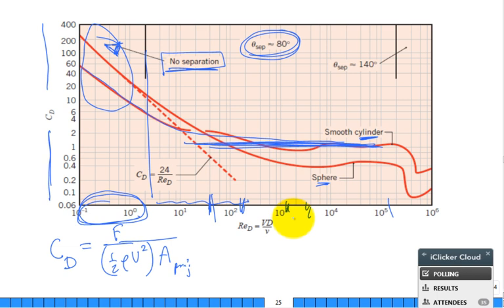But, roughly. Then out in here, they really increased the flow, and there's this dramatic drop. There's a dramatic drop in the drag coefficient, meaning there's a dramatic drop in F, the total drag force, because 1/2 rho V squared is only going up. The V is still going up at higher Reynolds number. So to really get a drop in this drag coefficient, you had to have a drop in the drag force on my cylinder. And this is very interesting.